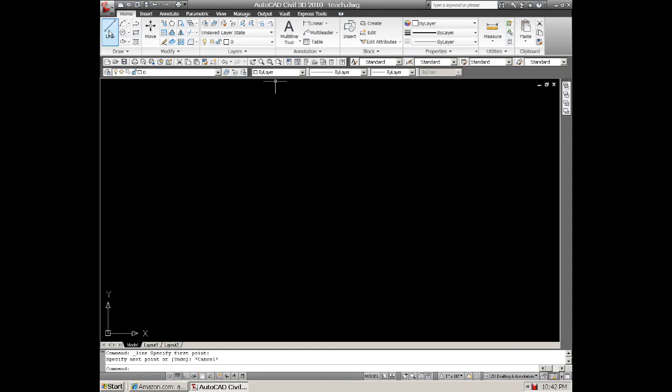So if we just do the first one here, we'll just draw a line. You click on the line again with your left button on your mouse, click, and you can draw a line. And you notice down here, always look at your command line, because that's where it's going to tell you what to do. It's not always interactive just up here with the mouse. There are ways that you can click on some tools down here to see what you're doing, but you always need to look at your command line while you're drawing. It says, okay, what's the next point you want to go to?